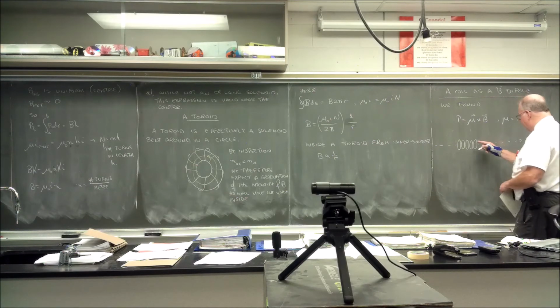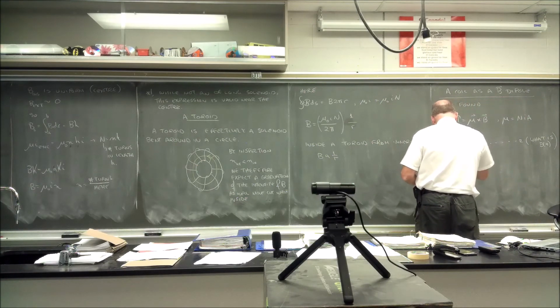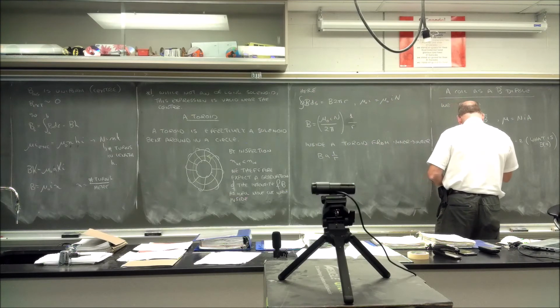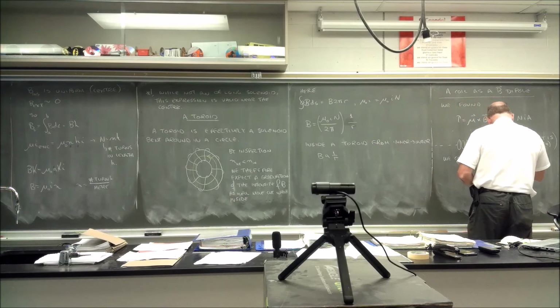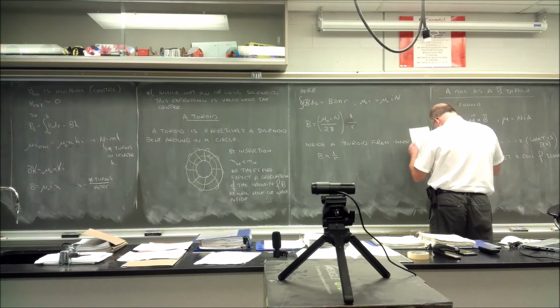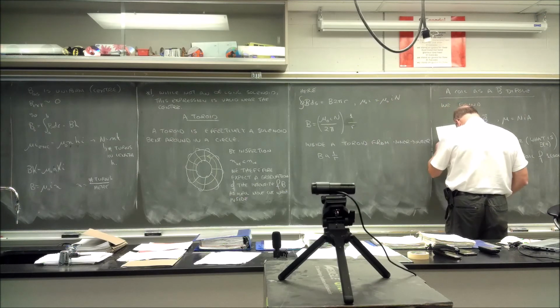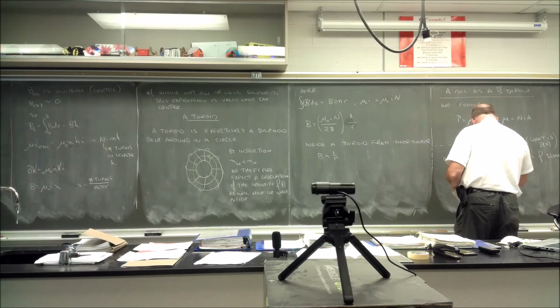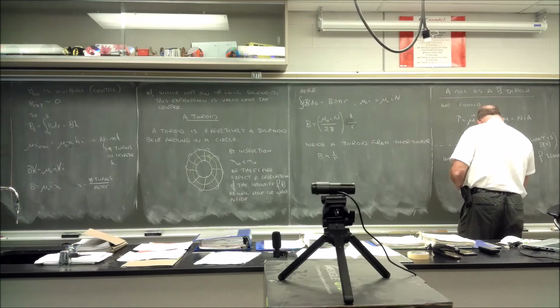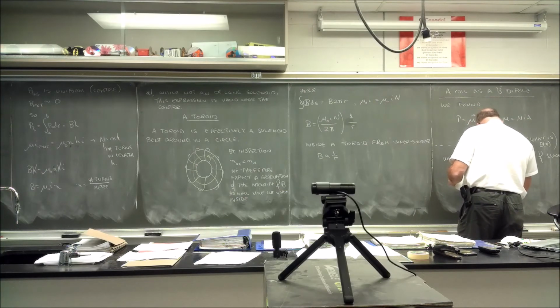And we can kind of get away with it here because of the symmetry. We consider first a coil of one loop, just to make it easier. Then we have B of z is equal to mu naught I r naught squared divided by 2 times (r naught squared plus z squared) to the 3 halves power.